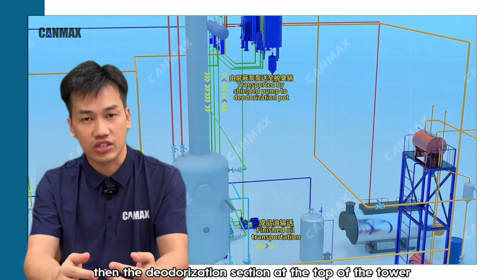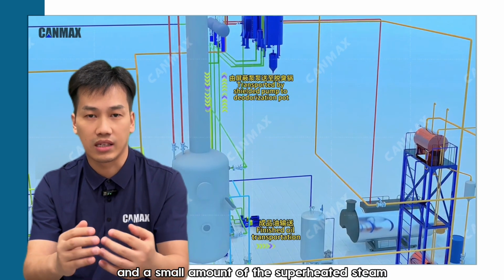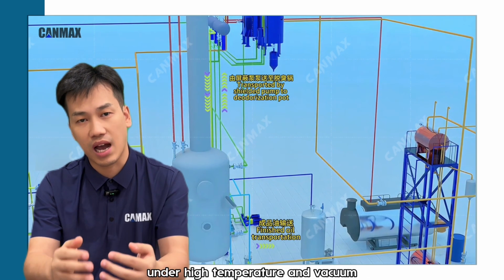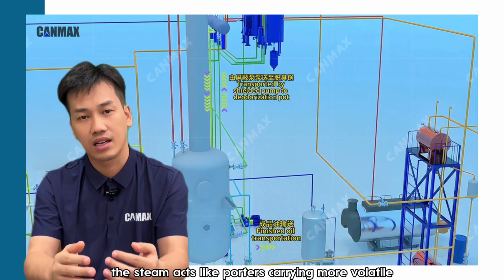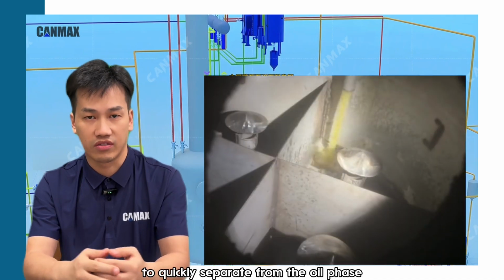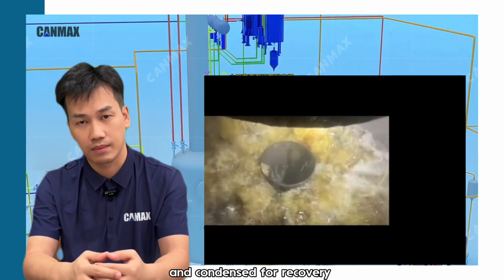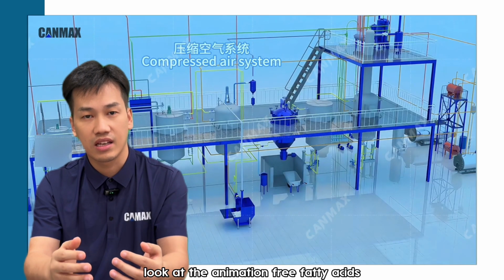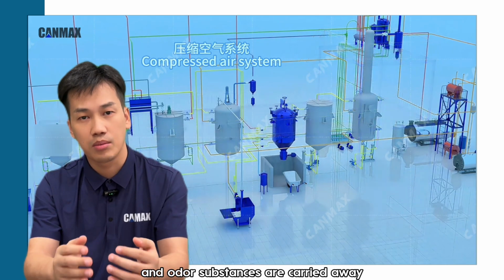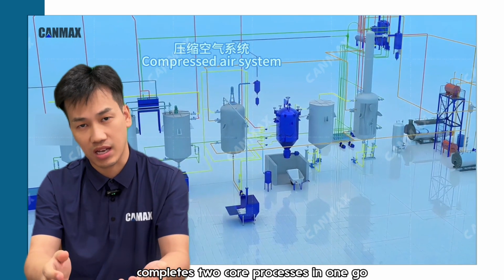Then the deodorization section at the top of the tower. The deacidified oil continues to flow upward, and a small amount of superheated steam is injected from the top of the tower. Under high temperature and vacuum, the steam acts like porters, carrying more volatile odorous substances to quickly separate from the oil phase. Finally, they are discharged from the top of the tower and condensed for recovery. Look at the animation. Free fatty acids evaporate from the lower part, and odorous substances are carried away by steam from the upper part. It's really clever how one tower completes two core processes in one go.